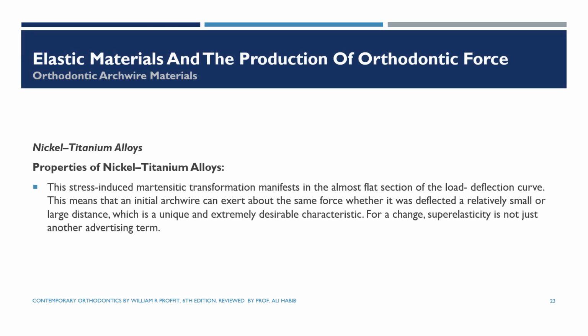This is what I explained in the previous slide, that this transformation manifests in the flat section of the load deflection curve, which means that the wire can exert about the same force whether it was deflected a relatively small or large distance, which is a unique and extremely desirable characteristic of these A-NiTi wires due to their superelasticity features.